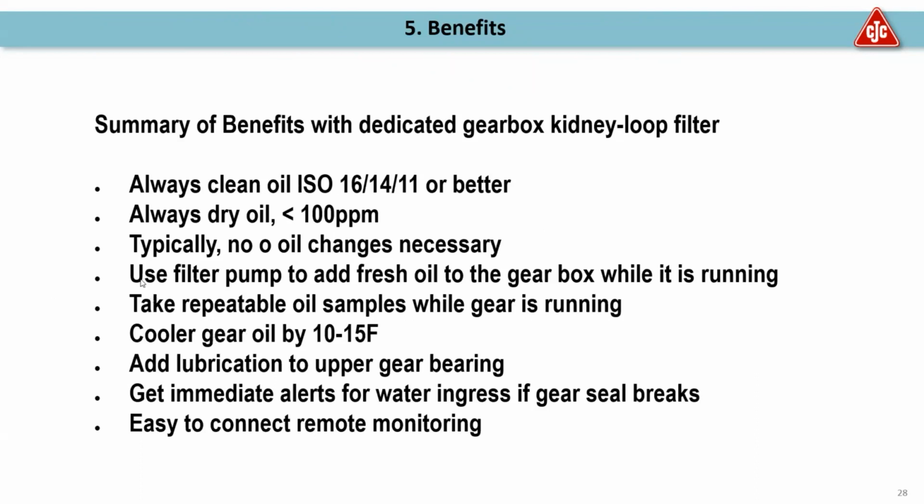Another benefit that we have found some customers made use of is using the clean discharge of the filter to add fresh oil to the top bearing. You can use the filter pump to add fresh oil, as already mentioned. You can take repeatable oil samples while the gear is running.